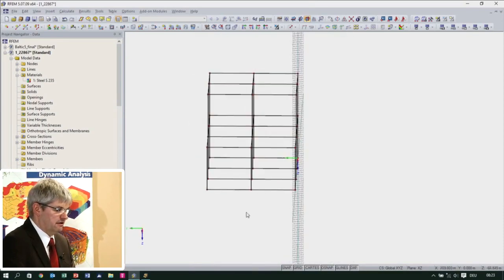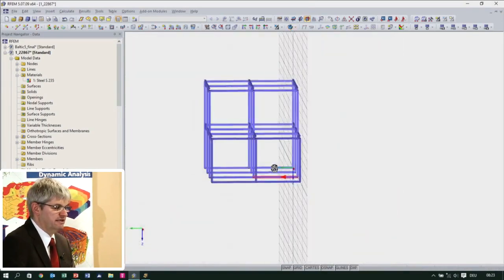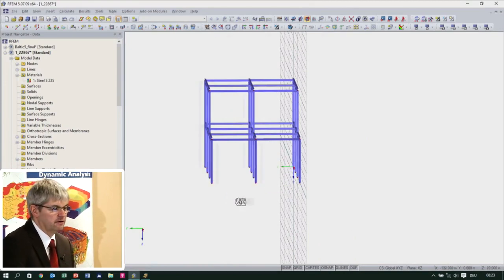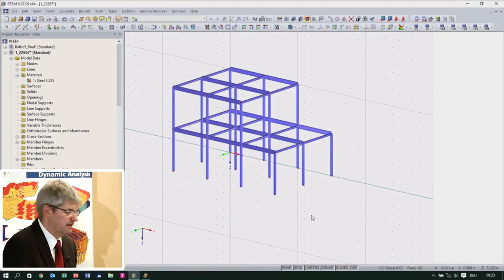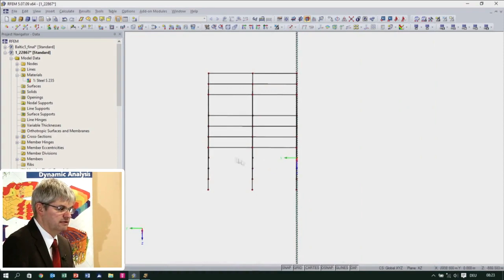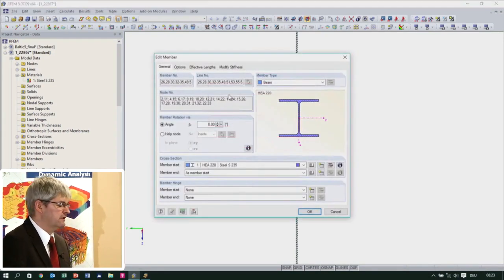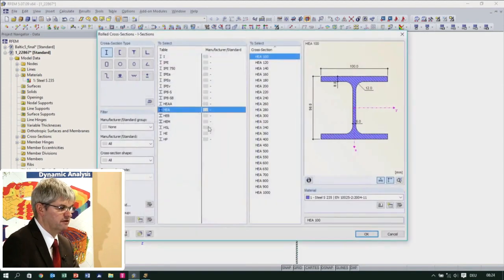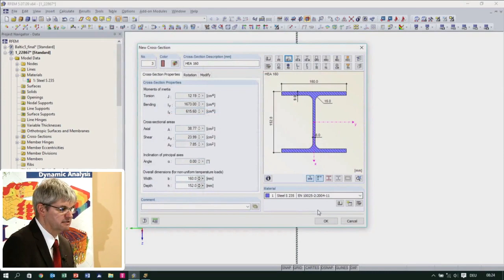The good thing now is if I do something wrong, I right away see it. I can quickly select it, delete it, and fix up my model as I want it to. When I do this, I have the option to do multi-selection, again with the crossing function. When I have a selection, I can double-click on the members, and I can assign new properties to this member. Like I can say, oh, I want to have a different cross-section here. Let's say wide flange 160.